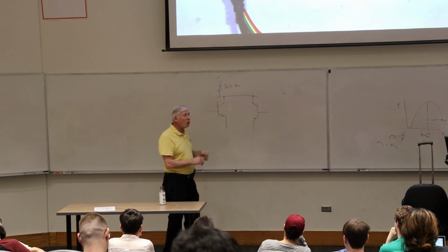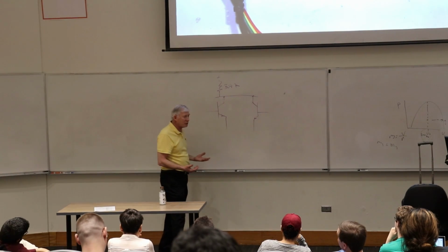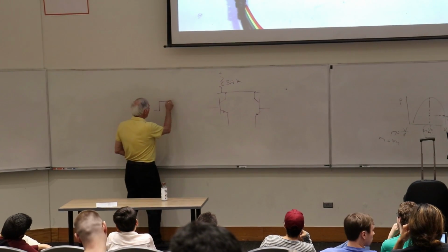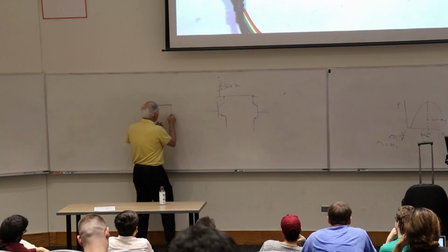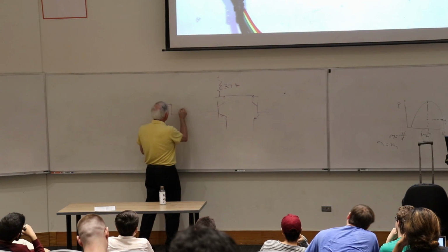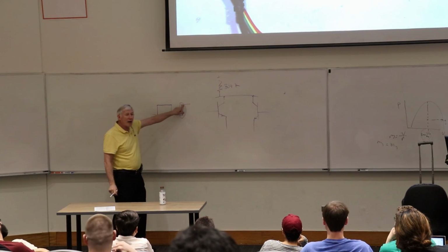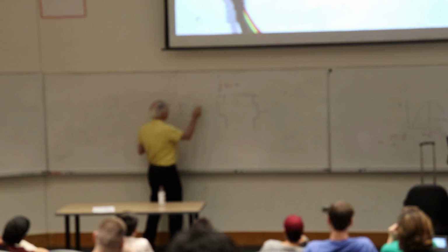So it works well for multiple devices where you don't want to worry about bus contention, something trying to drive at the same time. So what happens then in clock stretching? The master lets the clock go high, and then after a period of time they pull it low, leave it low, and then let it go back high. When the master lets it go, it expects it to go back high, and the master checks to see if in fact it goes back high. Because if the slave is clock stretching, then the slave may hold the clock low for an additional period of time, and that's the clock stretch.